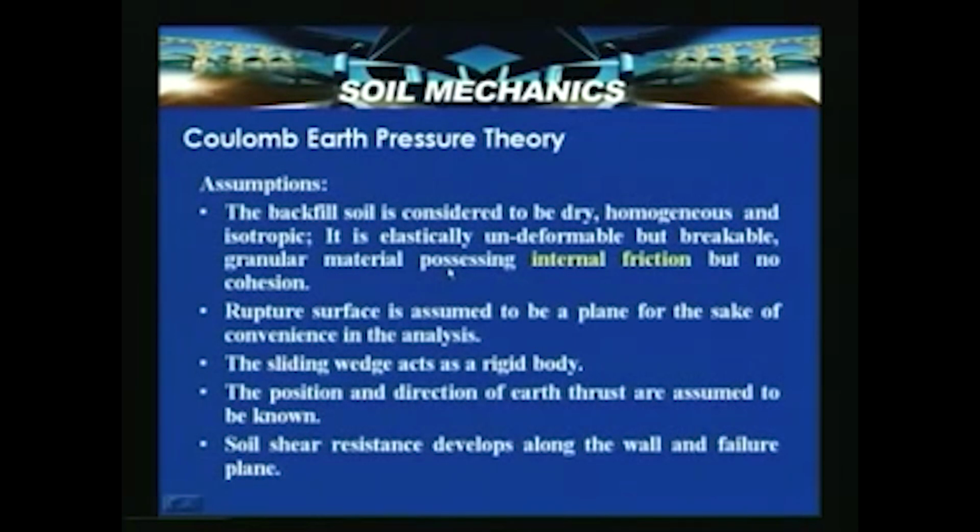Now let us look into some assumptions involved before discussing Coulomb's theory. The backfill soil is considered to be dry, homogeneous and isotropic, and it is elastically undeformable but breakable. It is a granular material possessing internal friction but no cohesion. So it is basically postulated for cohesionless soils.